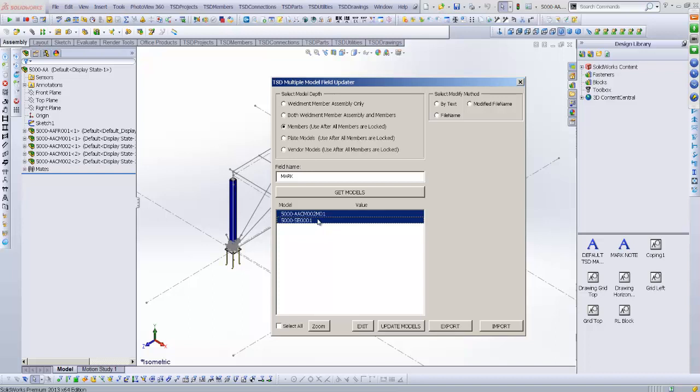Now, in theory, the best time for you to do this is when you've locked all your models or you're at the end of your project and you've finalized all your drawings, because it will automatically update once you've set up your templates, and we can swap the templates out as we need be as well. It's best that you do that, because if you go and create your plate numbers, you'll find that because there are the same plates in a project, your plate numbers may end up all out of sequence after a lock. So you're better off doing it after a lock. You'll see that when you try it. So don't do it. Lock it, then change your plates. It'll be less painful for you to deal with.